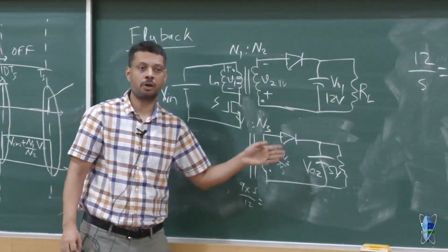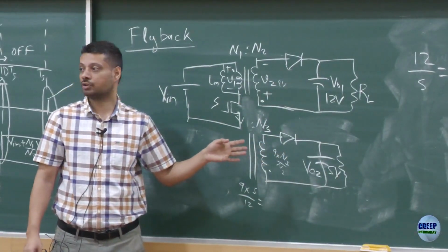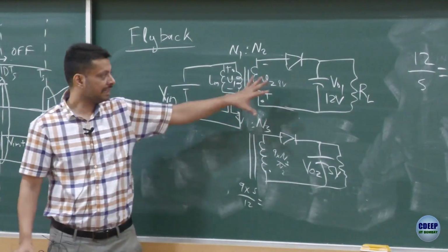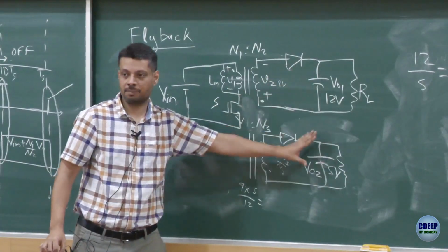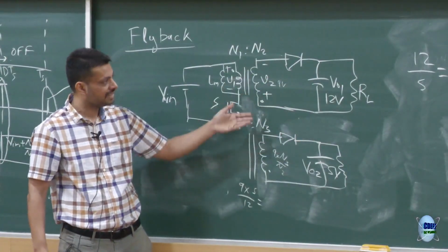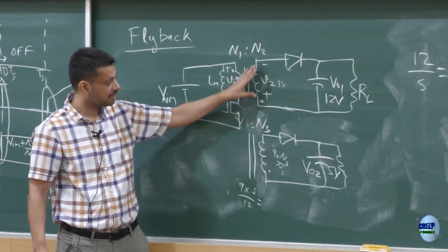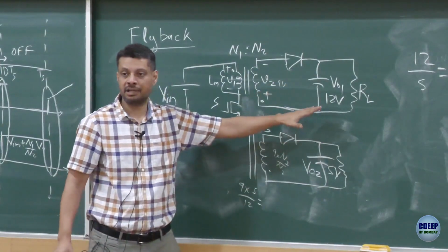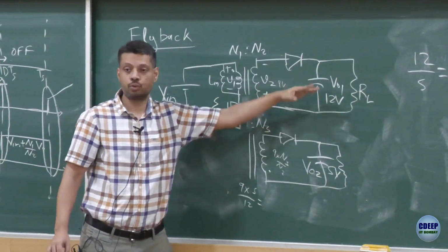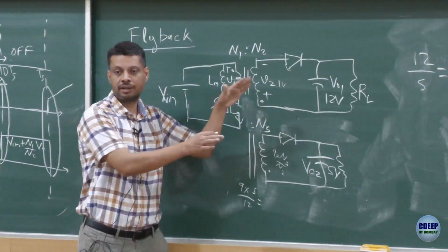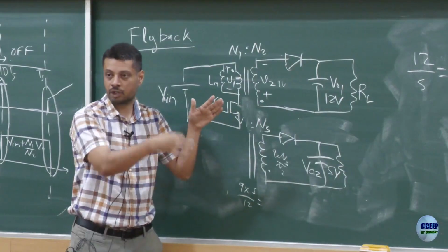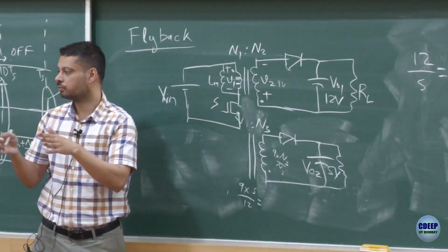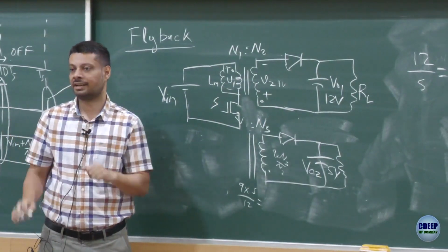This is very similar to common cathode configuration, but it's a little bit different picture, but it's the same principle. Basically, there are two diodes. Output side you have some voltages, input side, in this case they don't have common voltages, but there is a turns ratio, so common cathode configuration. So whichever output will be less than the desired value, that diode will conduct, shoot it up, bring it to 12 volt. Once it is 12 volt, then both diodes may conduct simultaneously. If one of the voltages drops suddenly, 5 volt goes to 3 volt, then again majority of the current will start flowing into that output, it will bring it up, and then it will try to maintain both of them.